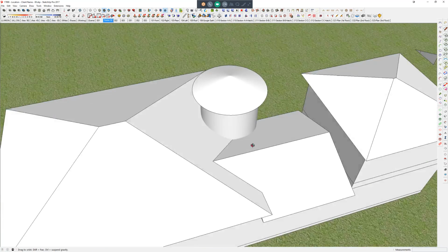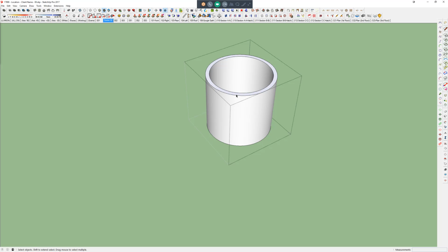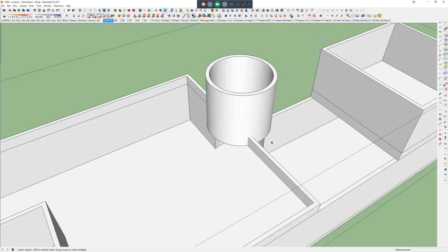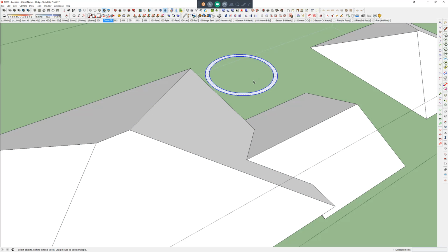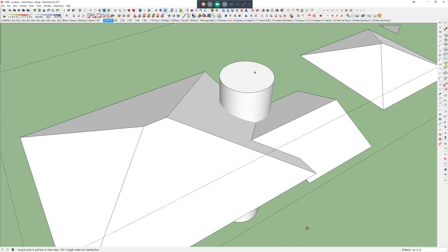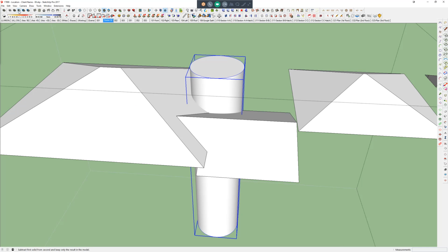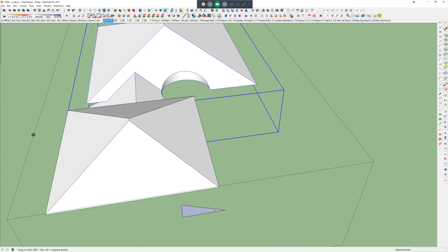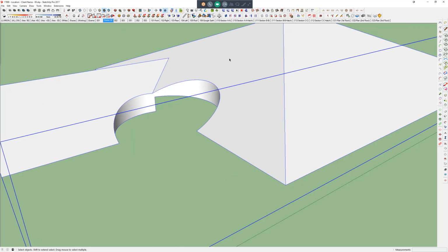And even ultimately, the way this roof is, I would come in here and grab essentially the ring of my circle. I'm gonna hide this upper roof, so I have my tower that I can drop straight through. I'm gonna turn this into a solid, and now using my subtraction, I'm gonna subtract this tower from this roof. And now if you were to try and model this thing by hand, how difficult would that be?